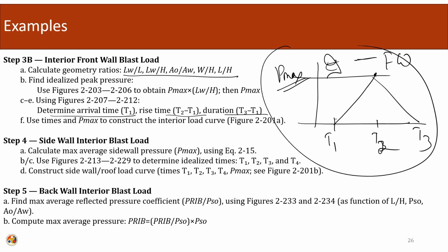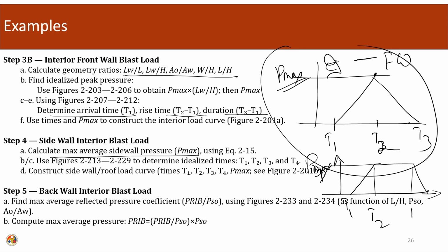After that, using the same equations, we calculate the pressure on the side walls, and this is P max. We calculate the pressure on the interior side walls. And after that, using the same equations, we calculate the back wall interior blast loading.